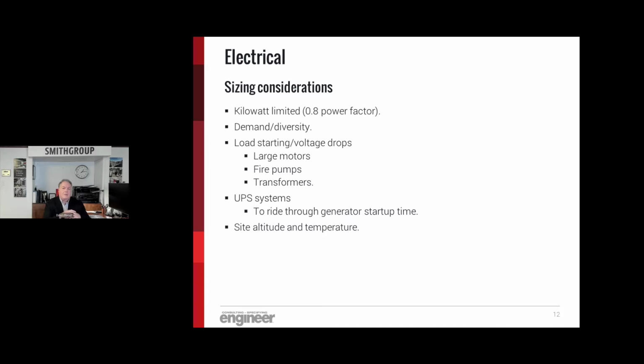But in addition, you need to look at the window when the UPS goes to battery and when the generator comes on, because generators may allow a little dirtier power than the UPS wants to see from the utility. And you don't want your UPS going to battery while you're on generator. Lastly, for consideration on sizing, make sure you understand the site altitude and temperature constraints of where you're placing these generators, particularly when they're outdoors, and check with the vendor about any derating based on the site altitude or temperatures.